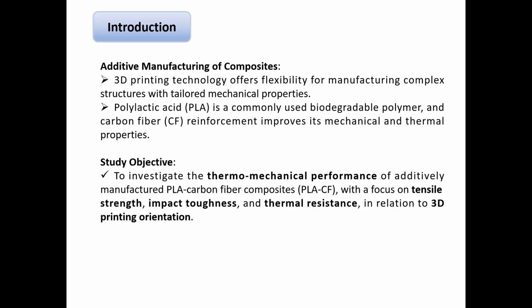Our study objective is to investigate thermomechanical performance and to find the difference between PLA and PLA CF with carbon fiber particles. It means it is a composite with carbon fiber particles. In our experiment, we focus on tensile strength, impact toughness, and thermal resistance, all in correlation with 3D printing orientation.